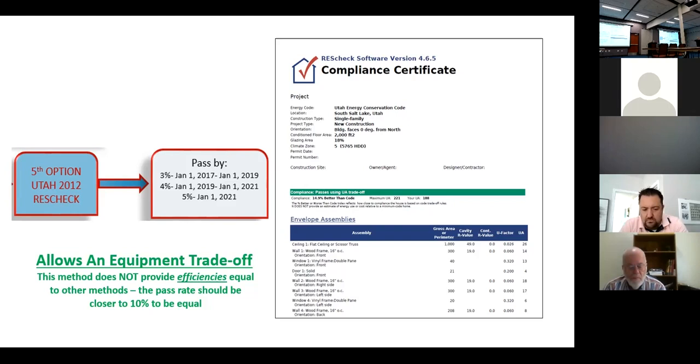This plays into it, but the question is why is, let's just say a 3-story apartment building, we don't build it out of the IRC at all. We build it out of the IBC and the IMC and the IPC and everything else, but we use residential energy. And it's because ASHRAE makes the division between low-rise and high-rise residential buildings. And ASHRAE has defined it 3 stories or less as a residential building. And so to just try to match ASHRAE, that's why a 3-story residential apartment building, no matter how many units, you have to use this versus ComCheck.